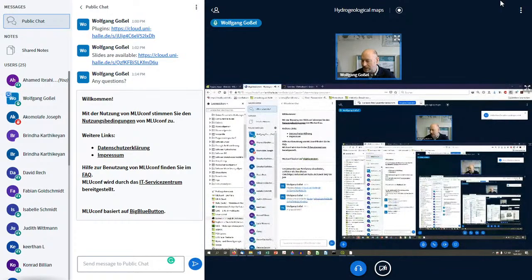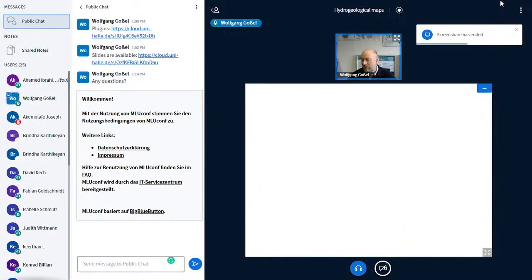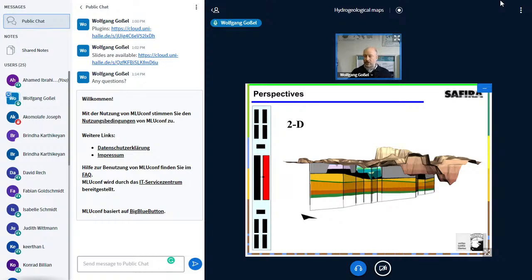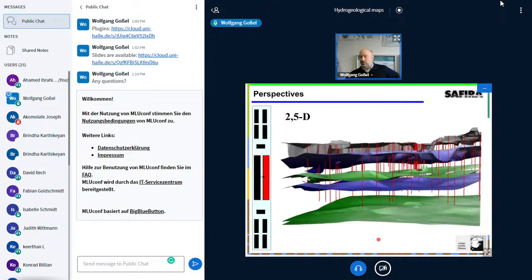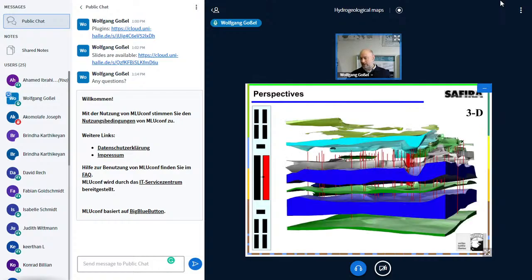Okay, let's continue here with our slides, because this is more transparent. So we start normally with cross-sections, in this case geological cross-sections, and we connect these cross-sections, as we did yesterday. We first of all outline the lines along the cross-sections that separate certain layers, hydrogeological units or geological units. This doesn't matter here too much. And then we, this should be on one of the next slides, we get surfaces or bottom faces.